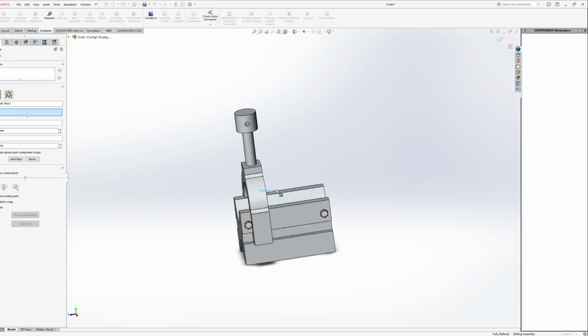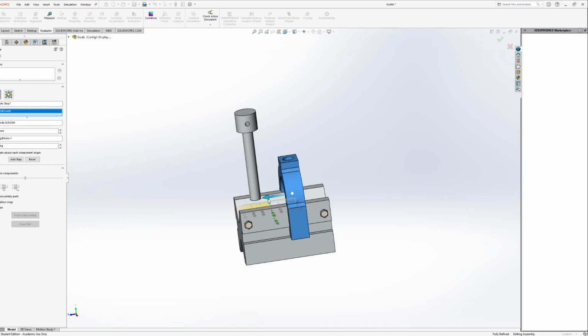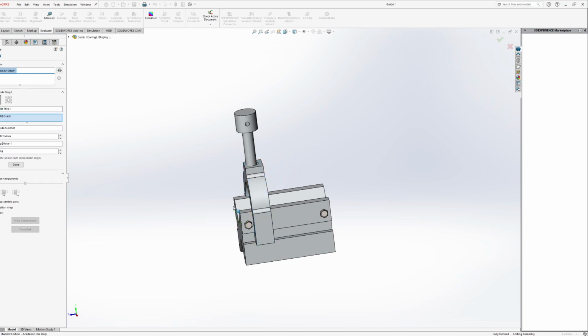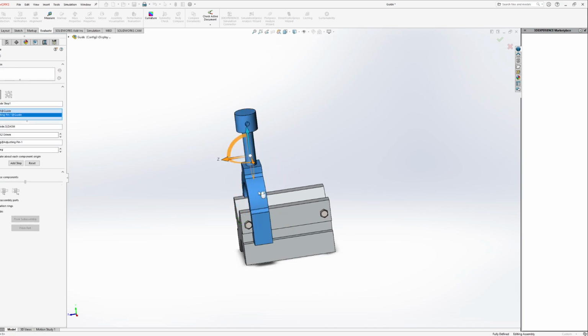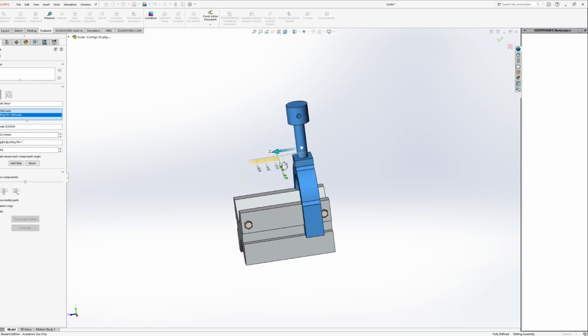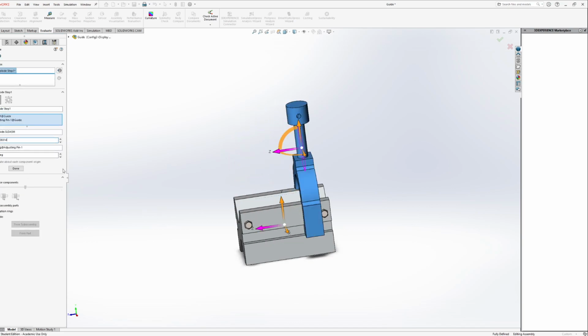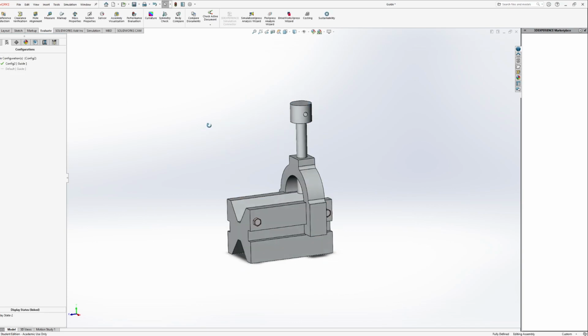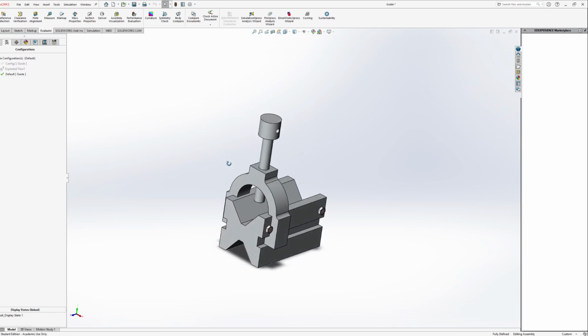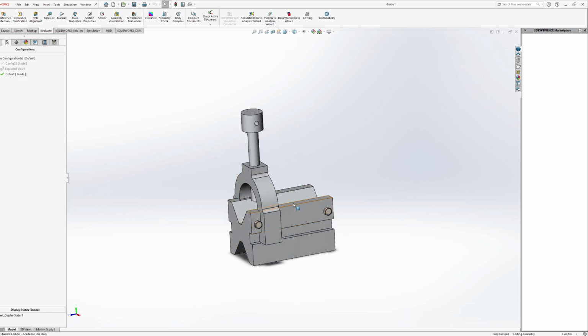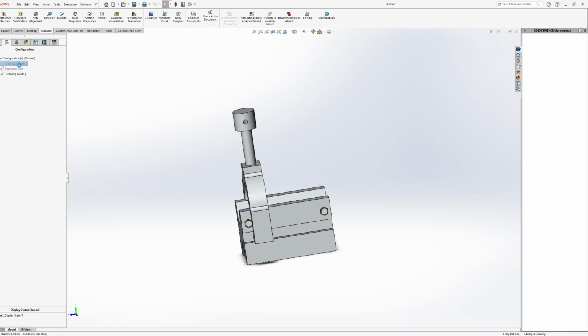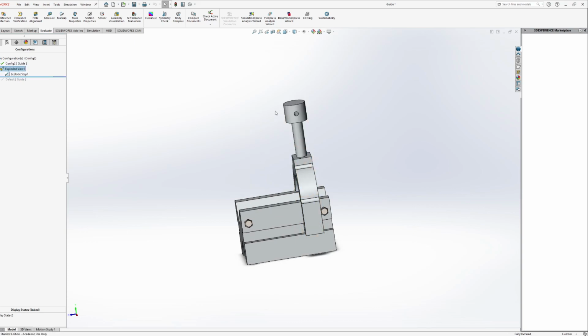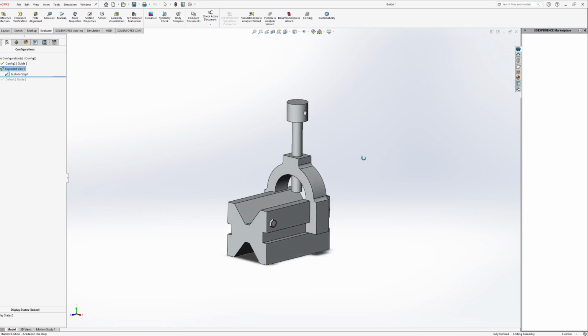And honestly, I'm really just going to move this. Ah, crap, it's going to do that. I'll just move all of these parts to the opposite end over here, which I already said should be 57 millimeters. There we go. And then just hit OK. And now I could say that in one of my views, the default has the yoke on the left-hand side, but for the exploded view, it's on the right-hand side.